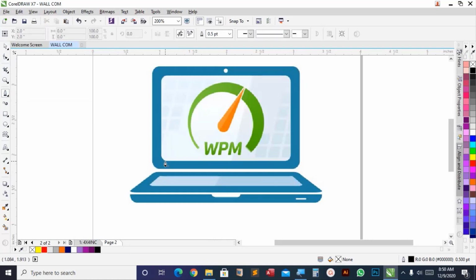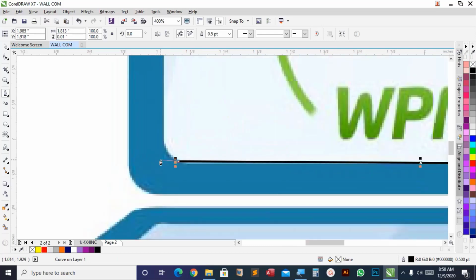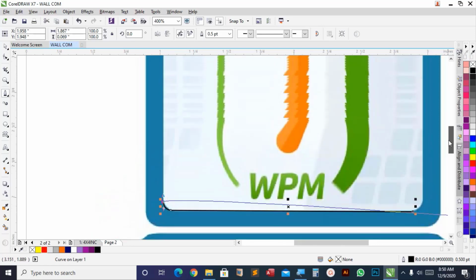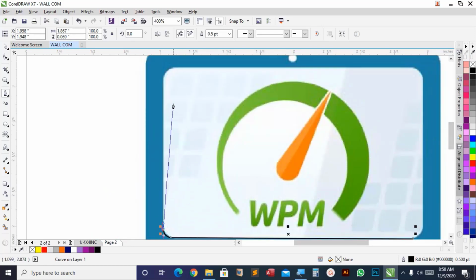So this is it. I'll come right here first, click once, and then come here, click once again. Alright, so when I come here, you see that it is a curve. So I'll click and just drag a bit, just a bit. Alright, now I'll go straight again because it is a straight line. So I can just hold my shift key down to have it perfectly done, then I'll click once.